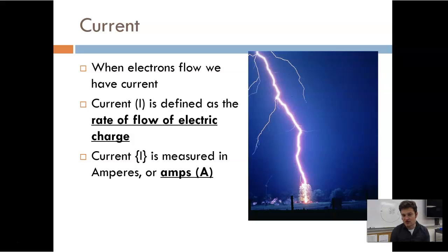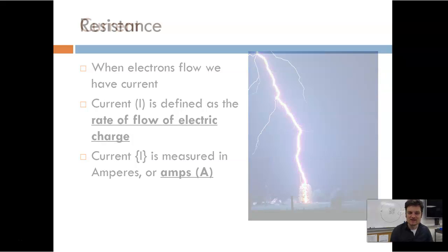One of the things you do have to worry about, though, is if we accidentally short circuit any part of it, which means you put a wire between two spots where there shouldn't be one, which has happened to a couple of robots already, that short can cause a burst of high current, and that high current can kill a motor or kill a sensor or stuff along those lines.